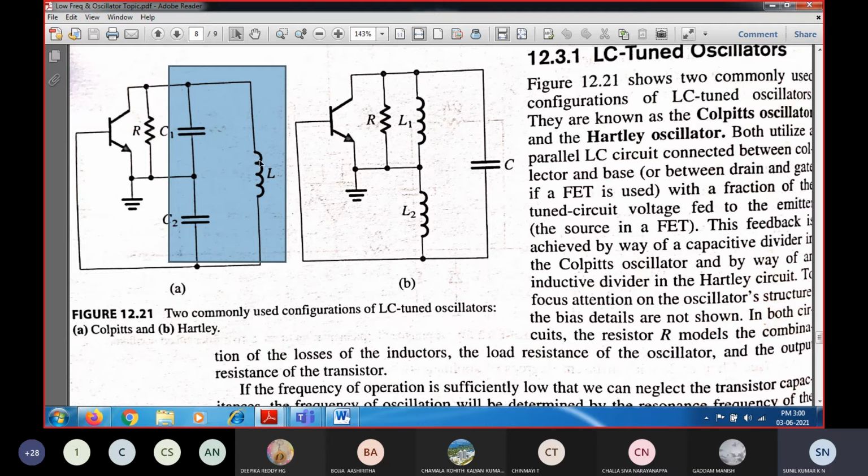Because of this back EMF, the inductor is going to make the capacitor discharge and regain the charge in the opposite way. When the capacitor discharges completely through the inductor, the inductor is going to recharge the capacitor in the reverse fashion because of the back EMF current.